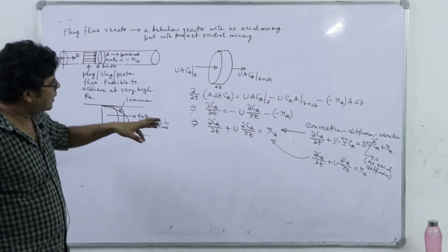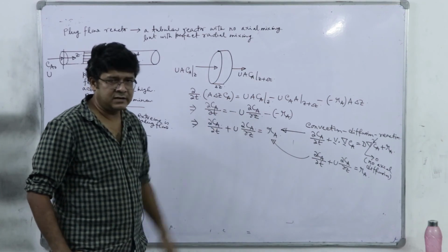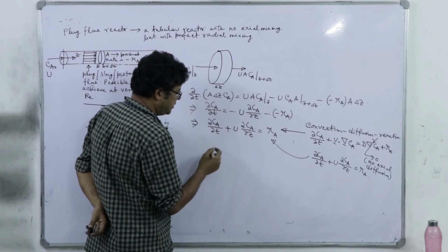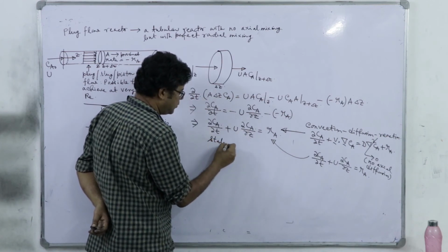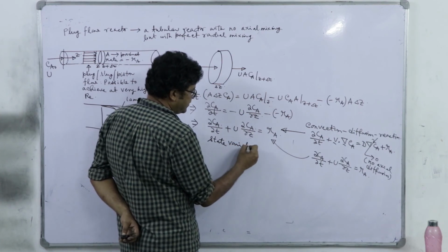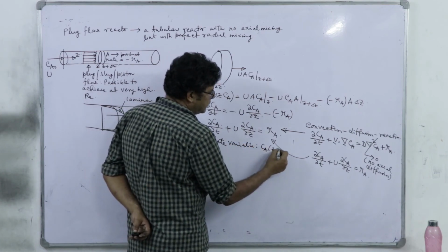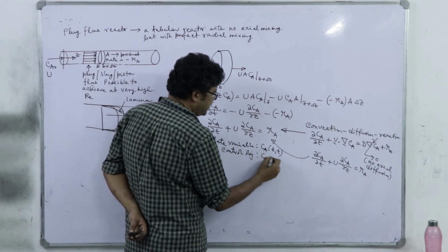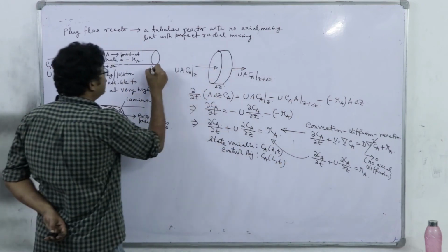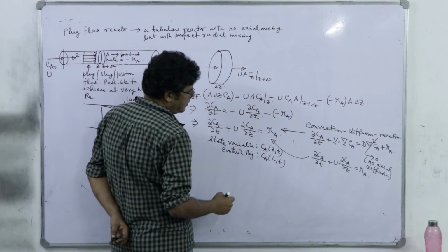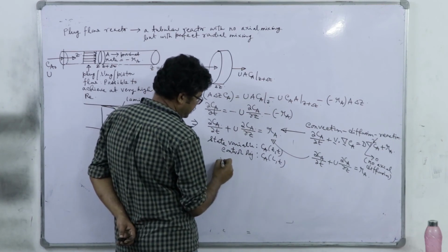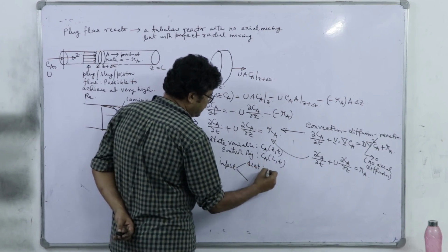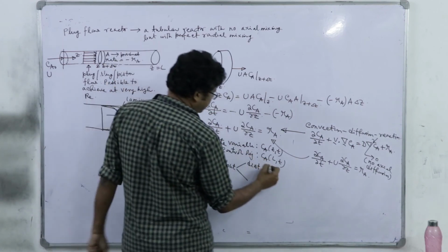Now, if I think of a steady state equation, let me first discuss the state variable and input-output. The state variable is CA(z,t), and the control objective is CA(L,t), where this is z equal to L. Then the disturbances will obviously be u and CA0.